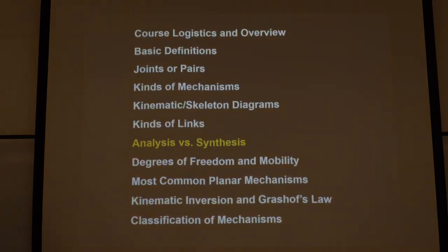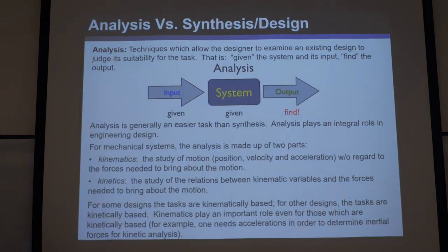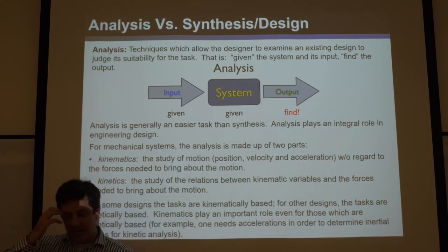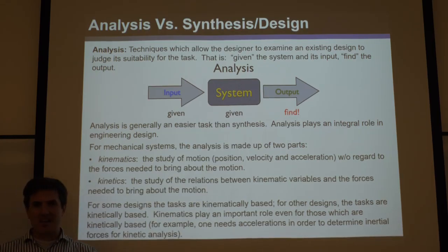Okay, so the difference between analysis and synthesis, and then we'll be done with this first little video here. Analysis, and there's a lot of words on the slide, but it's actually a really easy slide. Analysis is, I give you a mechanism. You know what the system is. Say it's a 4-bar, say it's a slider crank mechanism, whatever it is. I give you that mechanism. You can measure it. You know its lengths. You know everything about it.